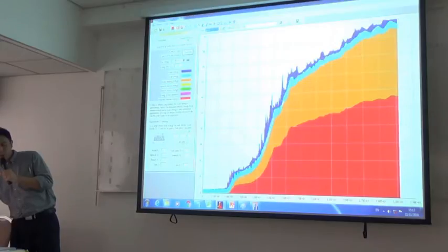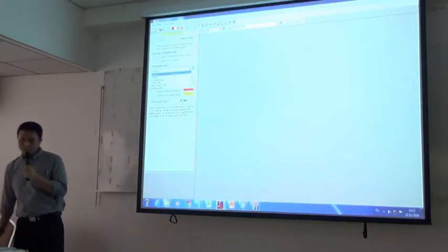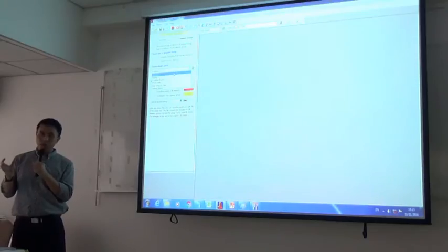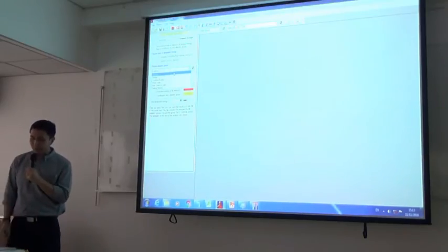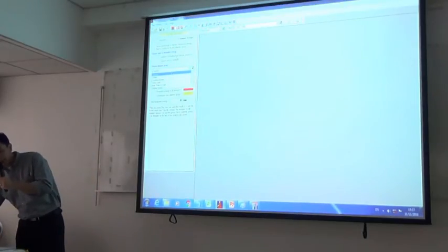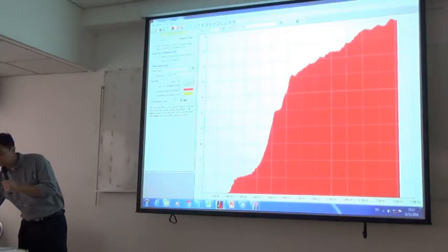Then we will go to another tab, here element groups. Then we can select the element group that we have defined. From those groups, we will check how much energy is dissipating from each group. First, I will select the shear walls. Then click the plot button.